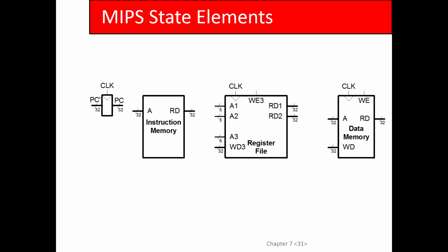But this is our instruction memory, and then we have a register file, which is a RAM, an SRAM. But this one is just like the instruction memory. It's just a RAM, except it's smaller. Notice it only has a 5-bit address. So this guy is 4 billion deep, and this is 32 deep based on the address. But it has more ports on it. It has 2 read ports and 1 write port.